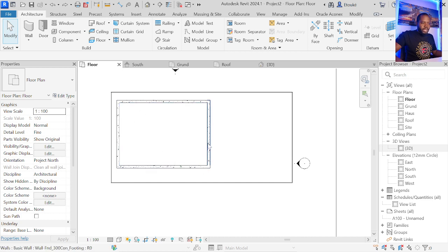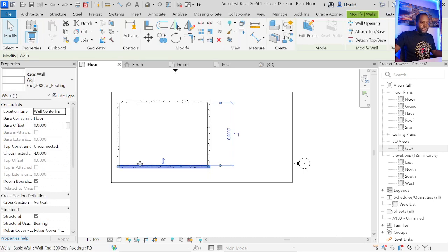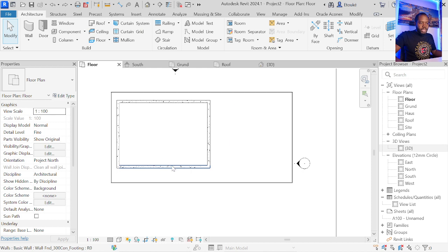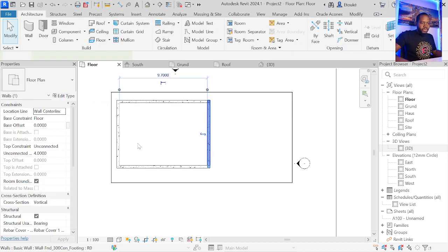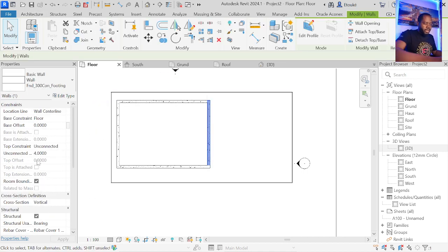We can just go back, and now what we will do is to divide our house, to start to give more. Let me check. It's 4 meter height, so we have to change it. This one we want to be 3, so we correct the others. Also this, everywhere has to be 3 meters high, so that is why we are changing it.